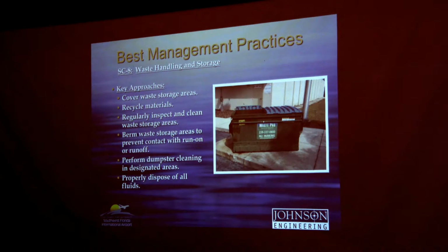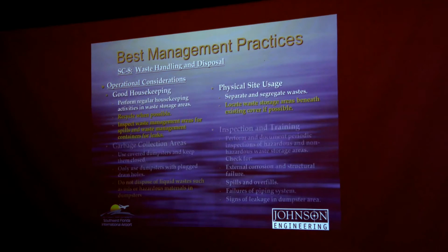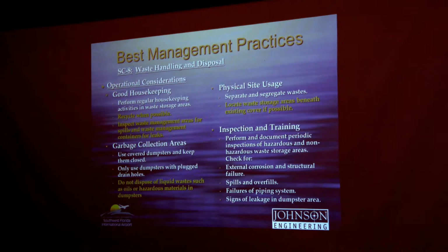All right, SC8 is waste handling and storage. Key approaches here include cover the waste storage areas, recycle as much as you can, regularly inspect and clean the waste storage areas, berm the areas to prevent contact with stormwater run on or run off, perform dumpster cleaning activities in designated areas, and properly dispose of all fluids. Additional considerations include regular housekeeping activities.